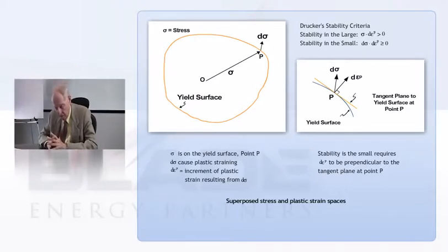The main effort that he has is sort of like an energy method. And he imagines that he has a yield surface, and you can see that's the cloud on the left. There's a zero place for the stresses, and there's a little sigma vector there. This could be the pi plane.